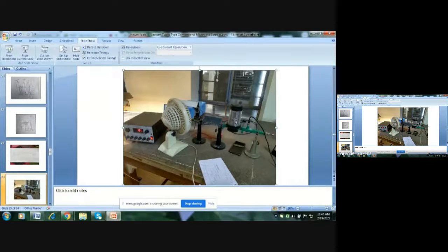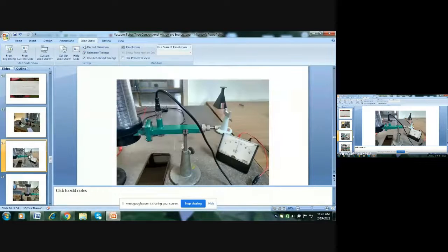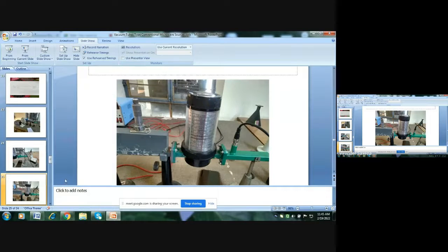There is a vertical red line and two horizontal red lines, and this vertical line between these two horizontal lines indicates the direct frequency. So in the Klystron experiment, we have to measure frequency at every point where we are getting power. So this is the indicating meter. This is the frequency meter.